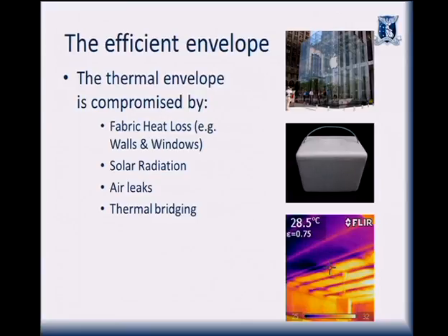Thermal bridging. What you're looking at is the ceiling of a room. It's actually my parents' house, believe it or not. In the yellow portion up here, that's where there's insulation. So the camera is seeing that the plasterboard is warmer where there's insulation above it. So it's warmer inside than outside in this situation, okay? So the heat's rising, it's getting to the plasterboard here, and it's staying warm because there's insulation above.